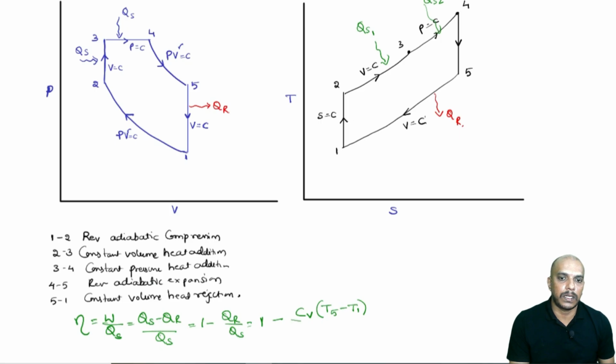in two stages actually. So, one is at constant volume and one at constant pressure. So, at constant volume we will have the equation Cv (T3 minus T2). See, this portion is constant volume. So, Cv (T3 minus T2) plus this portion 3 to 4 can be Cp, constant pressure, therefore Cp (T4 minus T3).